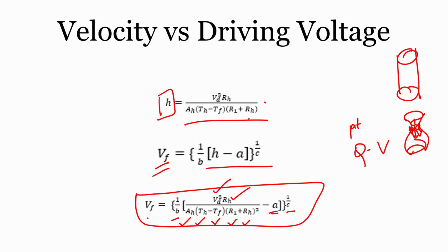When you have a sensor that can be introduced, and you already know the parameters of the sensor, that is the cross section area of the sensor and the resistance, all of this would be in the signal conditioning circuit outside. So, all of these parameters can be known, and the driving voltage changes only because of the change in fluid flow, and this way it becomes easier to quantify the velocity of the fluid in situ just by having a sensor of this kind.